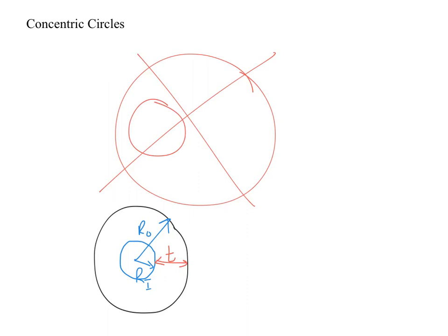So if you're talking in engineering or just modeling for home, if you want to know that the pipe has a certain wall thickness, you can take the outer radius and subtract the inner radius. If you use diameter, you have to take the outer diameter minus the inner diameter and divide by 2. Because you get 2 wall thicknesses then, right? Think about it geometrically. I'll show you another diagram on the right here.